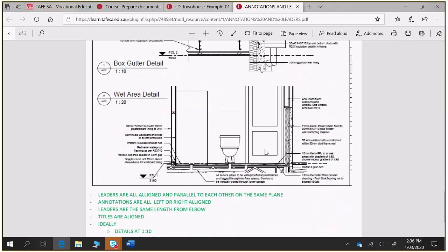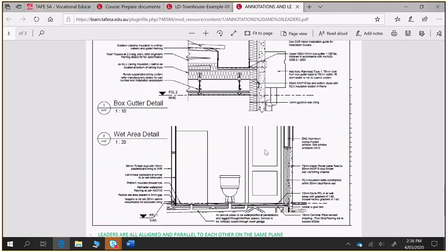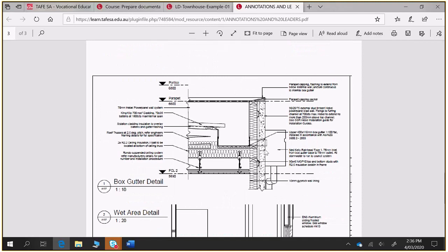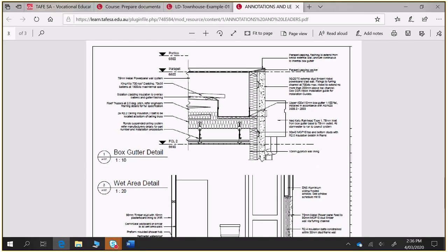And I encourage you to, if you've got the time, though it's not a requirement of this subject or this course, play with line weights. Using those 3 line weights that are set up in the drawing is suitable. The only thing I would ask you to do is, when you're doing a section and you're showing ground, thicken up that line. Make that a 0.7 or so to show the earth. That is one thing that makes a big difference.